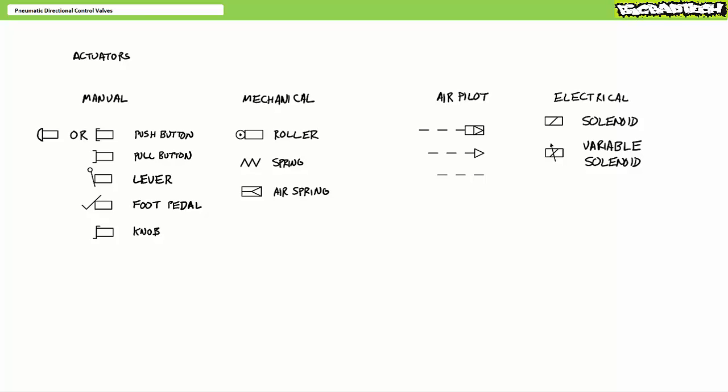In this manner, a variable solenoid as part of a proportional valve with a specially designed spool not only operates as a directional control valve, stopping, starting, and changing the direction of fluid flow, but also as a flow control valve by ramping up or throttling down flow rate, thus controlling not only actuator direction, but also actuator speed. We'll examine proportional valves in much later lectures.